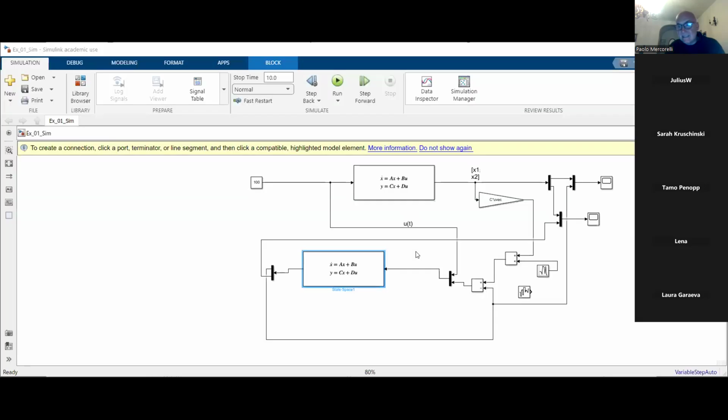Do you remember, L is calculated such that, let me eliminate this problem here. This is the noise, which we will see next week. Consider the problems which I have with the Luenberger observer. L is such that the eigenvalues of the observer are -200, -500. Let me run.